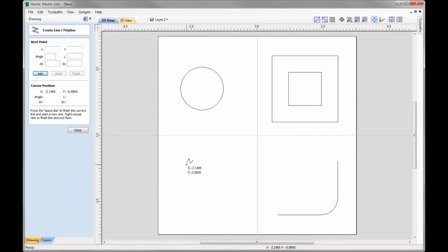So in order for us to start to draw where we align our drawing to an existing object, we need to wake it up. So to wake up an object, we simply run our cursor over the object that we want to wake up, and then we'll be displayed with various lines and extensions based on the object that we woke up.